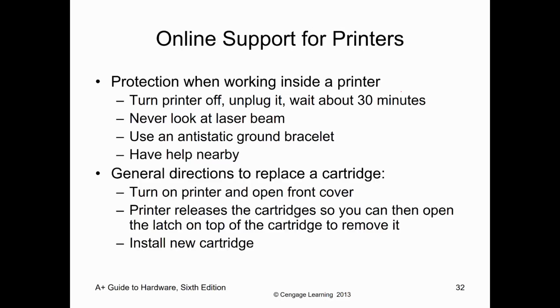So protection when working inside of a printer: turn it off, unplug it, let it sit for 30 to 40 minutes. It may hold a charge. If it's a laser printer, don't look in the laser. Maybe wear an anti-static grounding strap. Also, because we are working with printers, maybe keep someone nearby just in case. Printers can cause some serious damage, so we do want to keep that in mind.